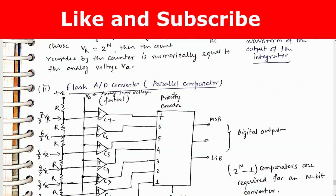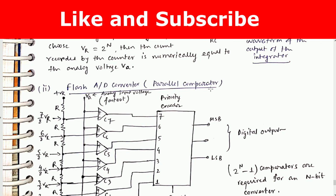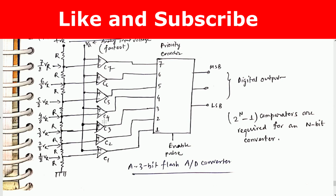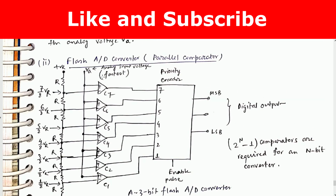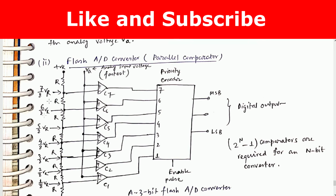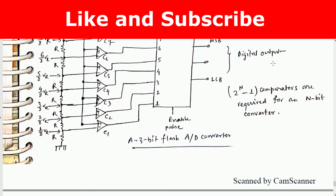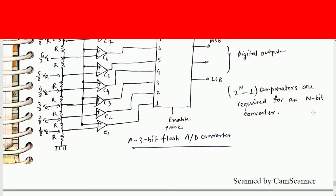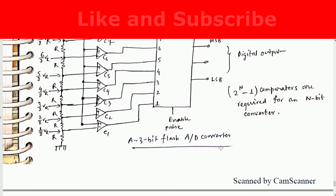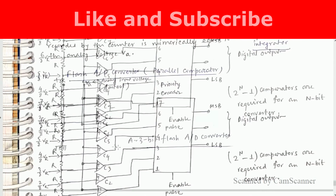Flash AD or parallel comparator. In this analog to digital converter, you will get so many diodes, so many op-amps, 1 2 3 4 5 6 7. Analog input voltage, V reference, priority encoder. So this is very easy to remember. Flash AD, digital output. 2 to the power n minus 1 comparators are required for an n-bit converter. This is a 3-bit flash AD. So 3-bit means 2 to the power 3 minus 1, which is 7. 7 comparators are required.